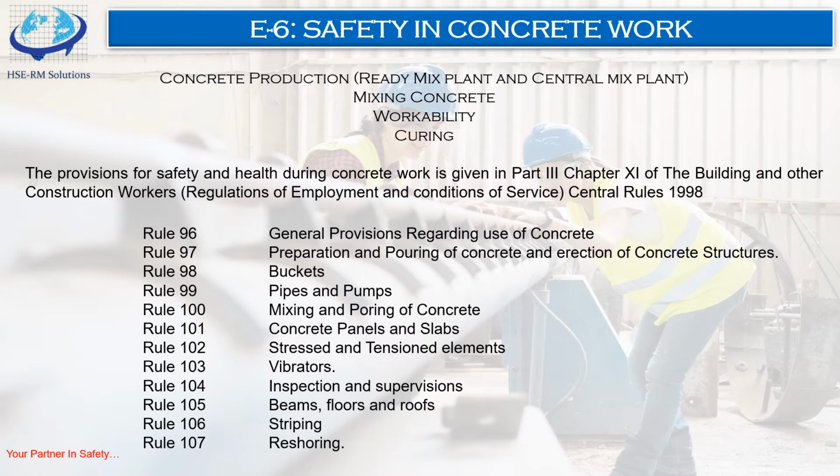Now excessive water leads to an increase in bleeding, that is surface water, and segregation of the aggregate, when the cement and the aggregate tend to separate, with the resulting concrete having reduced quality. The use of aggregate with undesired gradation can result in a very harsh mix design with very low slump, which cannot readily be made workable by addition of a reasonable amount of water.